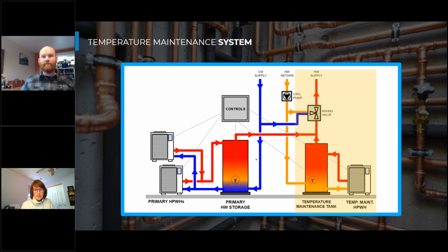We can also have the same thing, cold water or hot water draw. Someone uses hot water at the fixture, cold water comes back here. It's going to offset hot water, and that's going to go in a parallel connection to our mixing valve. When no one's drawing hot water, this pipe will not have fluid flowing through it.